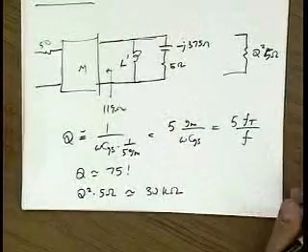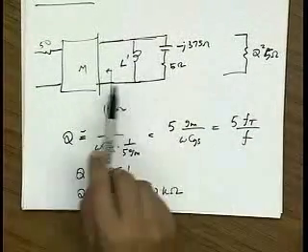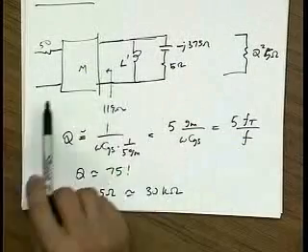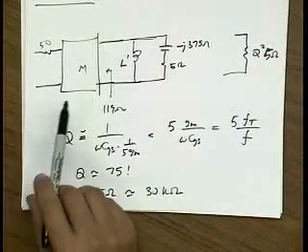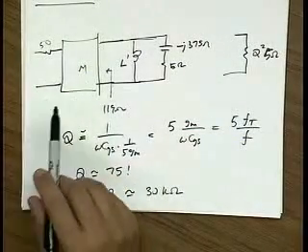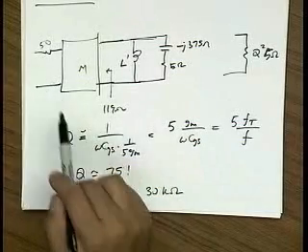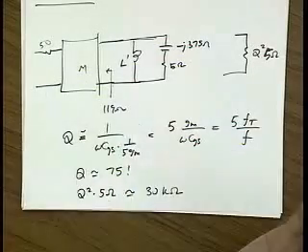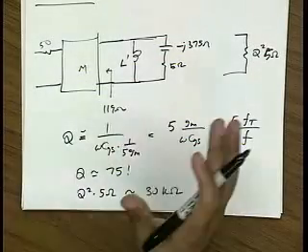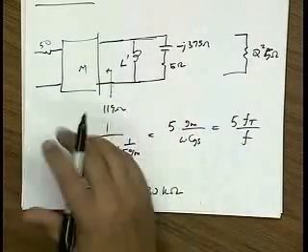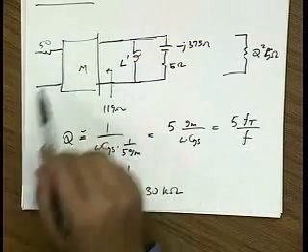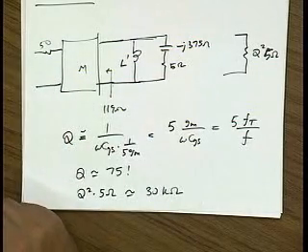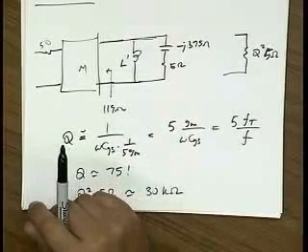So it's in fact not really the right value either. Now it's a very large impedance. If I transform this down by a factor of 2.5, I still have something on the order of 10 kilo ohms. Very bad impedance match. 10 kilo ohms at RF doesn't really make sense anyway. It's way too high. Realistically, the board and the parasitics will limit the impedance to hundreds of ohms, right? So again, this is a really bad option. Okay.